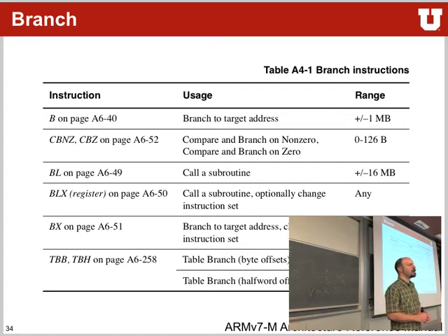The way of doing it will come later on. It's by setting the last bit to a 1 or a 0 of the jump address. Since you can only jump to 4-byte increments, the last 2 bits are actually used for encoding what you want to do. And sometimes you can jump to a certain address and switch the instruction set at the same time. That way, for example, the A application processors can have mixed binaries of Thumb and Thumb2, and they can be mixed in together.